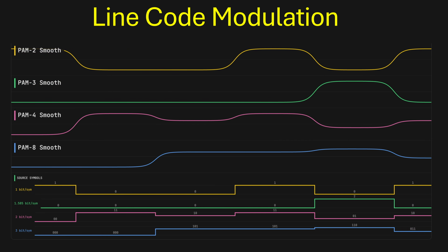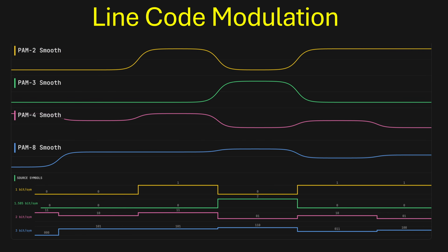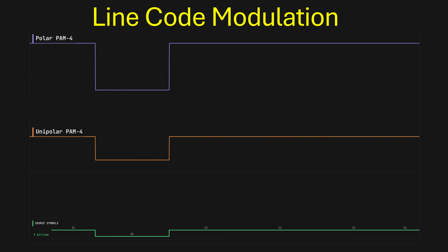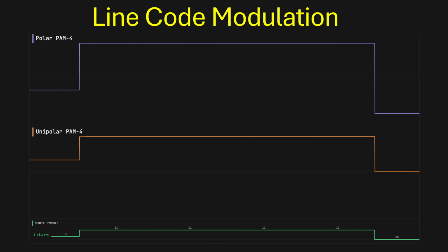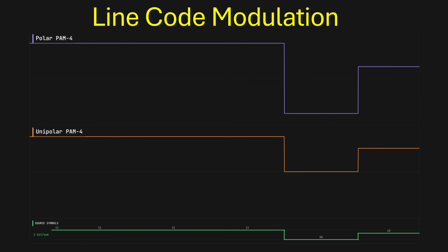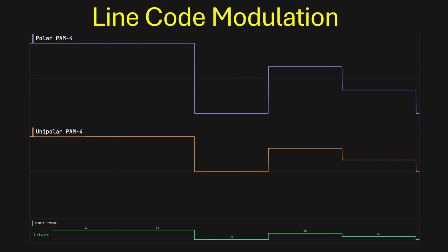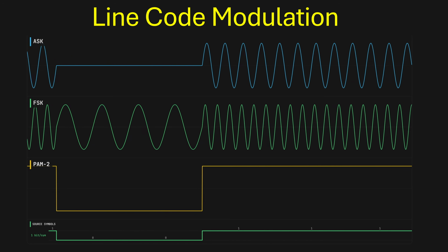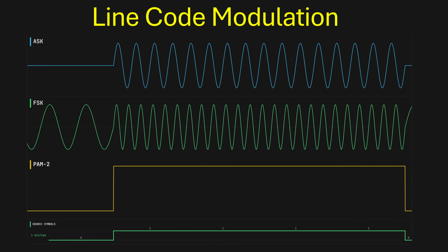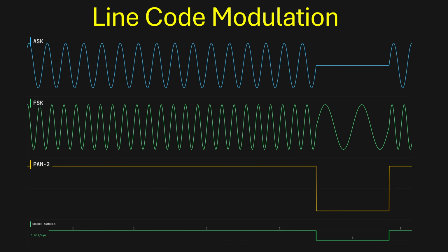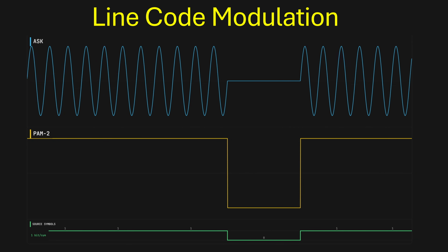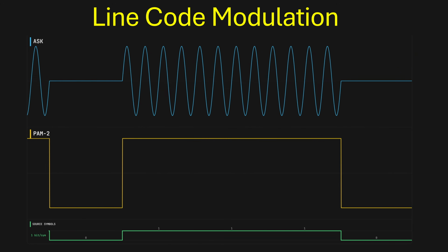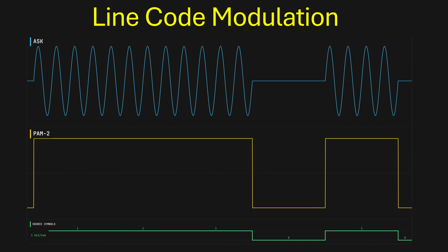Real signals have smooth transitions instead of being perfect square waves, but I'll sometimes show the ideal transitions for simplicity. In polar PAM, the signal oscillates between positive and negative voltages, which is why it can be called alternating current despite having no AC carrier sine wave. Some copper cables use passband, which modulates signals onto an AC carrier wave, like in RF, but most standards are baseband, meaning they directly adjust and measure pulses of direct current voltage. Here I plot an amplitude shift keying signal that's passband that could be used on an antenna versus a pulse amplitude modulation baseband signal so you can see the difference.